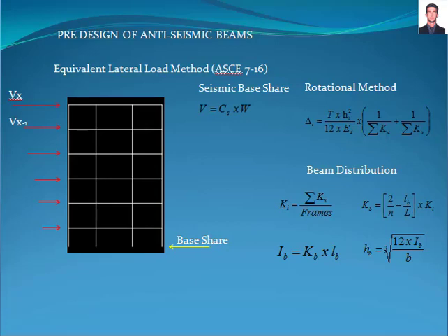After having pre-designed the columns, load-bearing beams, and slab of the structure, we are ready to calculate the total seismic weight and the seismic response coefficients to calculate the seismic base shear as requested by the American Society of Civil Engineers standard, and do the distribution of the lateral forces for each story.